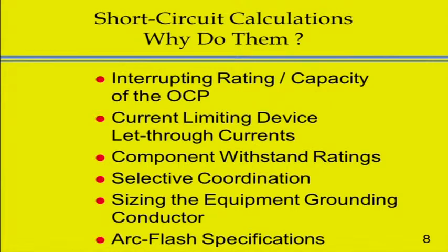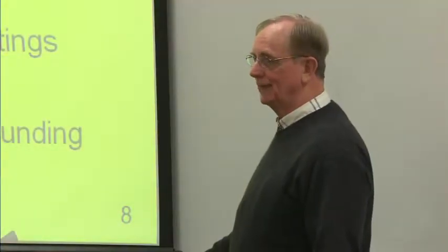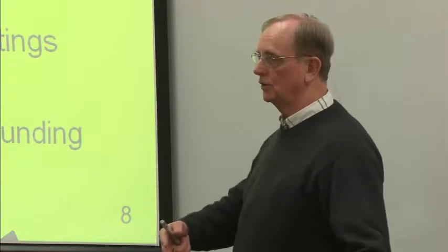If that is not set up that way, you can have situations where you can have a fault in one part of the building that shuts off the main to the building. Now you can imagine if you plugged something in this classroom and the overcurrent devices weren't coordinated and it turned the power off to the building if it was shorted out. That would not be a good thing. That has happened before in large buildings like this.